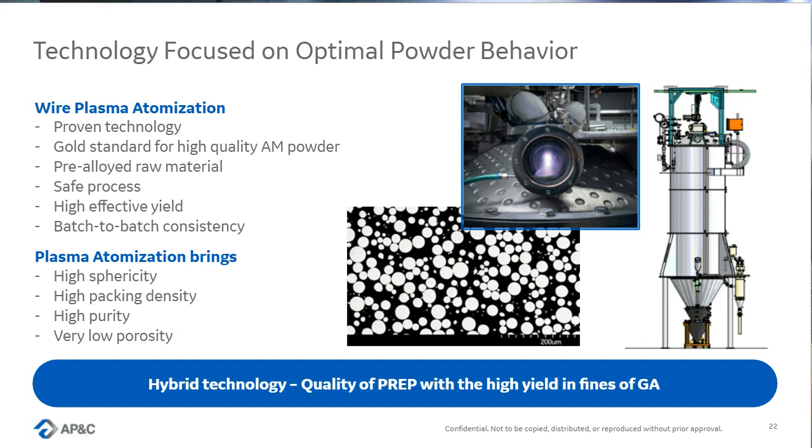Gas atomization, like IGA, also does, so this is something that we share with that technology. Pre-alloyed raw material ensures that you benchmark the years of the supply chain of titanium that's been optimized to have quality products. You take that same quality product and you just transform it one step further into a powder. You don't change the alloy chemistry, you just change the form.